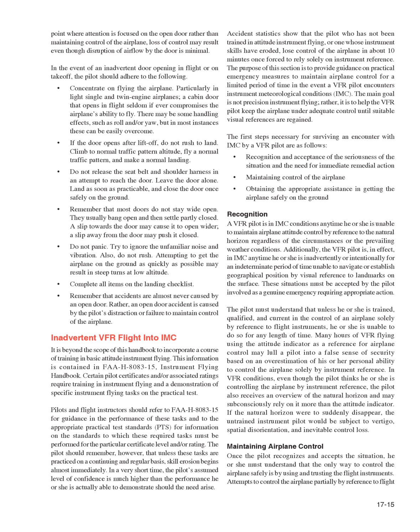Recognition: a VFR pilot is in IMC conditions anytime he or she is unable to maintain airplane attitude control by reference to the natural horizon, regardless of the circumstances or the prevailing weather conditions. Additionally, the VFR pilot is, in effect, in IMC anytime he or she is inadvertently or intentionally for an indeterminate period of time unable to navigate or establish geographical position by visual reference to landmarks on the surface. These situations must be accepted by the pilot involved as a genuine emergency requiring appropriate action. The pilot must understand that unless he or she is trained, qualified, and current in the control of an airplane solely by reference to flight instruments, he or she is unable to do so for any length of time.